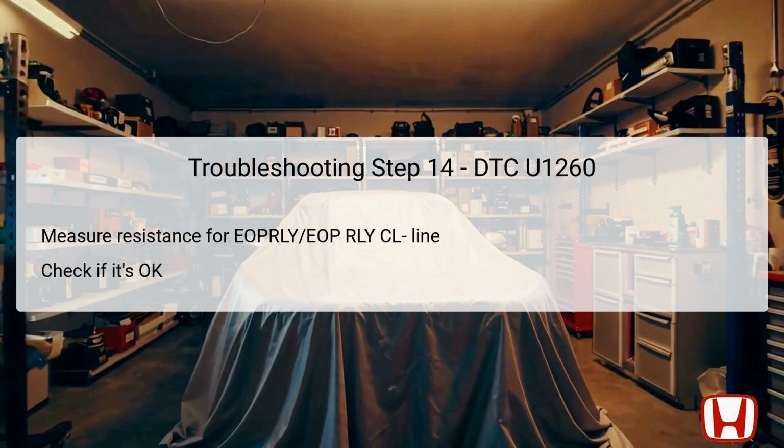If the measurement indicates a higher resistance value, it denotes an open wire that could impede communication or operation between the TCM and the auxiliary transmission fluid pump. Identifying and repairing this is essential for restoring normal operation.